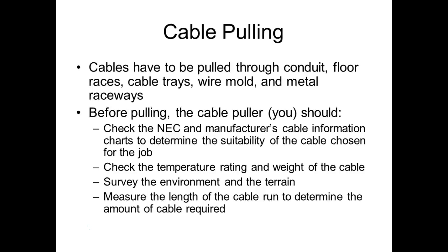So we had to run everything. We had to run the underground conduit. We had to trench it out, run the underground conduit, and connect it up to the feeder, and then run it into his house. So we spliced it. So we stagger spliced it, but we had to do what?